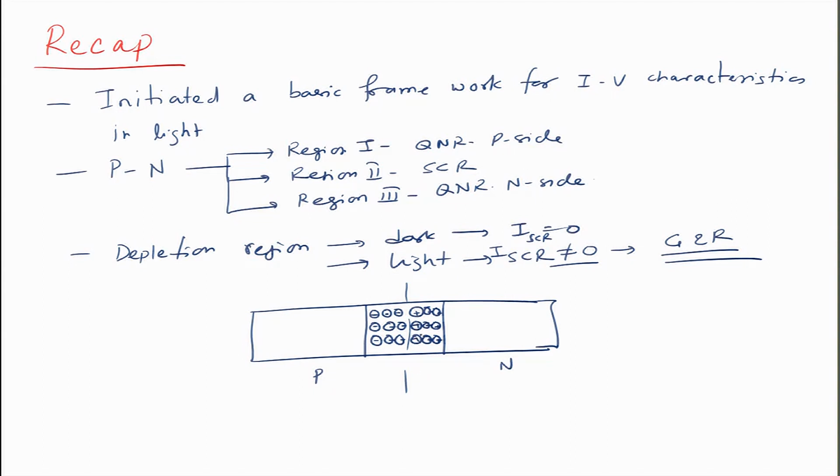It is a depletion region because every free hole and free electron is cancelled out here, they have neutralized each other. As a result, there are only ionic cores, but it still has a valence band and conduction band. So, if you look at the energy band diagram, it is something like this.